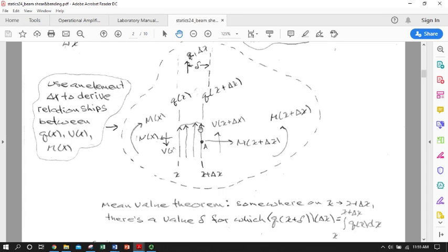Then we've just got the moment due to this upward distributed load. So we said if we had the function q, we could take the integral from point x to point x plus delta x. We can integrate the function between those two points as a definite integral and evaluate it, and then we'd get the magnitude of the resultant upward force over this distance.